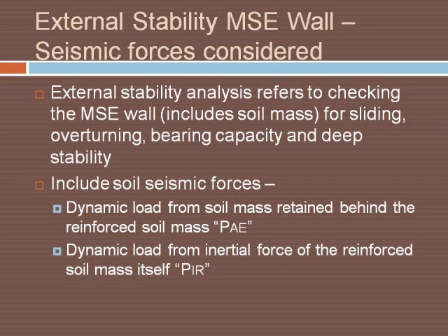Now we'll focus on external stability analysis, and it refers to checking the wall for sliding, overturning, bearing capacity, and deep stability. And it is to include the soil seismic forces P sub AE and P sub IR. P sub AE is from the soil mass retained behind the reinforced soil mass, and P sub IR is the inertial force of the reinforced soil mass itself.